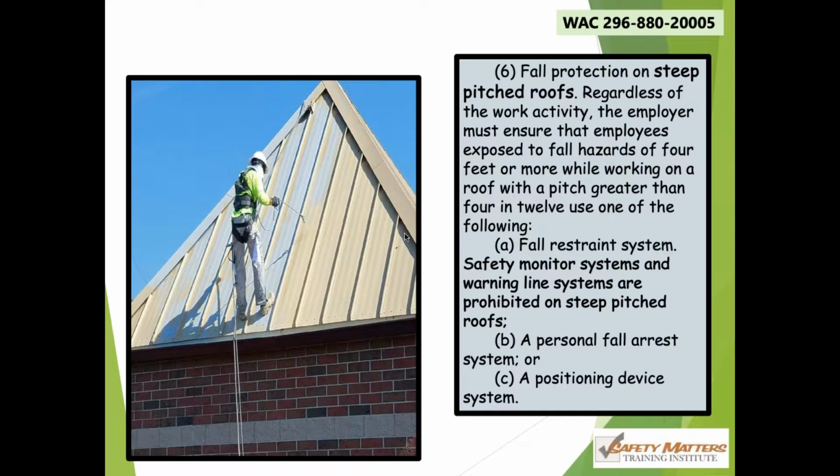Steep pitched? What's steep pitched? Steep pitched is any surface where I cannot maintain normal footing without the use of some kind of device. Steep pitch is always more than 4 and 12. Greater than 4 and 12 is a steep pitched roof.